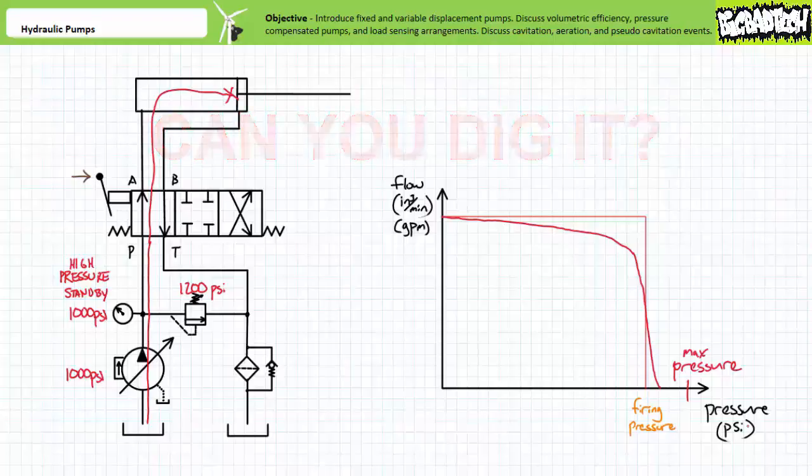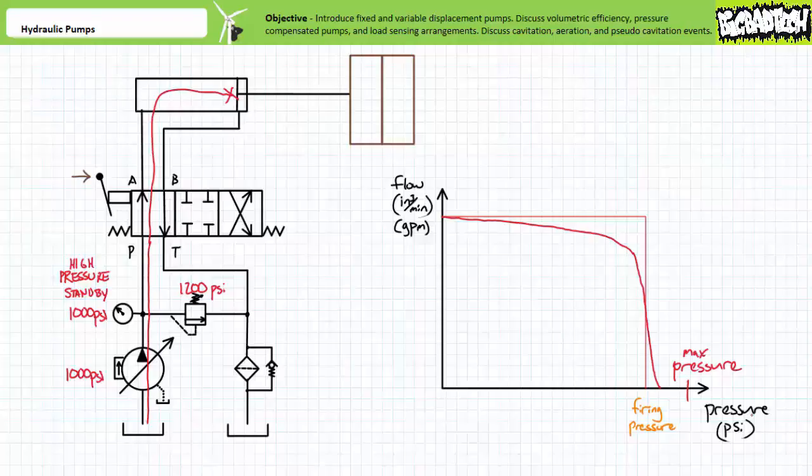In both scenarios, the closed center, and when the actuator reached the limits of travel, pressure rose to the firing pressure, and the pump simply destroked to 0 gallons per minute and stopped pumping when the circuit didn't need it. A pressure-compensated variable displacement pump can be used for applications necessitating an actuator extend with a given force and then maintain that force for a lengthy stall period. For example, a cylinder used to compress a mold. While the molded piece cures, the cylinder must maintain constant extension force, otherwise the final product would be damaged.